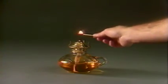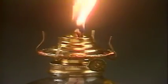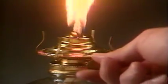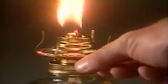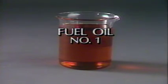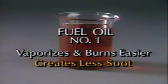This kerosene lamp is an example of vaporizing. As the lamp burns, the wick pulls the oil up from its dense liquid state in the base, exposing it to oxygen and heat, producing continuous combustion. The combustion is controlled by regulating the length of the wick. But combustion by vaporizing can cause excessive soot unless the fuel is completely burned. Number 1 fuel oil is the preferred fuel for a vaporizing oil burner. It vaporizes and burns easier than number 2 and creates less soot.